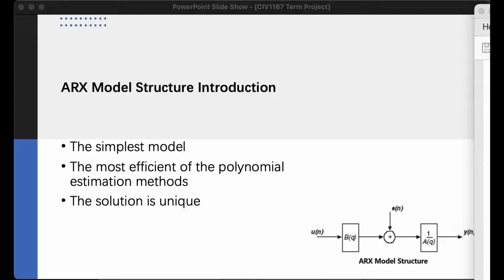In addition, the model validation. The main objective of model validation is to validate that the dynamic model represents the system response of the real process. The validation was done using one part of the experimental data that was separated using interlacing techniques.